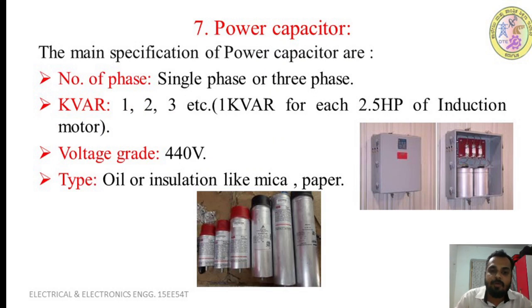Next, we have one more major component, the power capacitor. You know, all induction motors cause a low power factor, right? So for that, we have to improve the power factor. For improvement of power factor, we are using power capacitors. How to select the perfect capacitor? This depends on